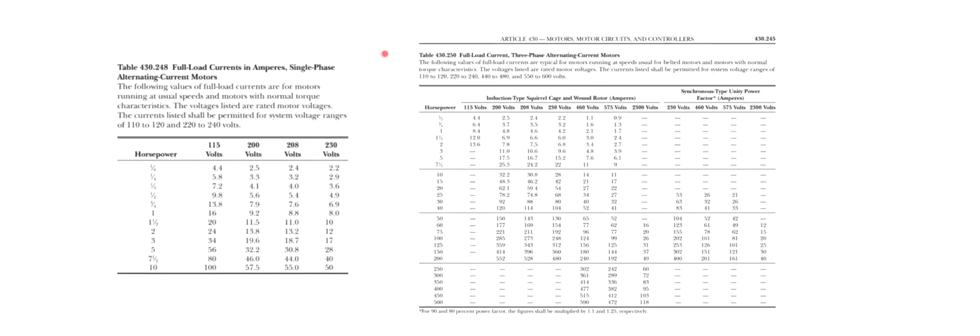Now, there are also tables back there, and I'm just shooting off the hip. You've got 430.249. I believe that's for, I think they call it two-phase motors. We won't ever use that table, and if you go past this table right here in your book, 430.251, I believe, is a polyphase motor. Won't use that. Now you may use, I believe it may be 430.247, and that's DC motors. So if you have a question on your test that's asking you about DC motors, that's the table you use. You don't use any of these that I just showed you.